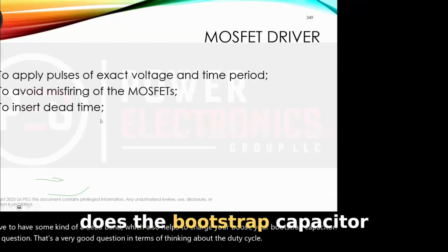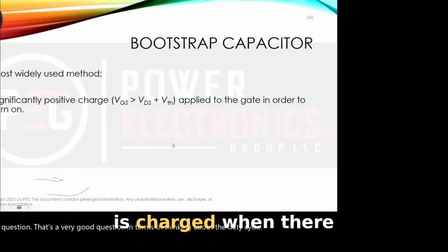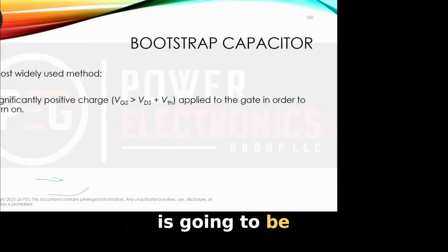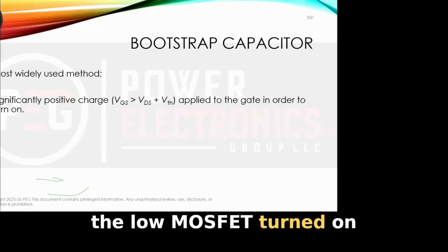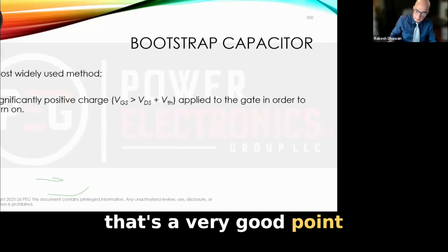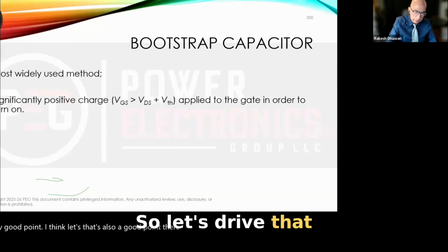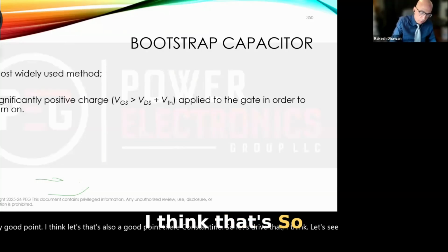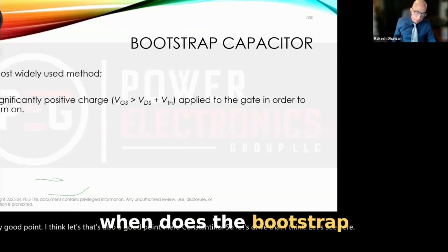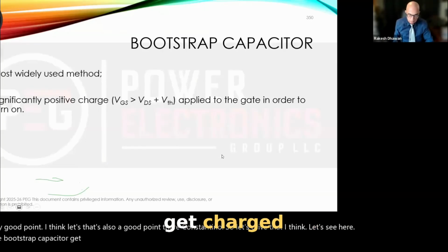Is the bootstrap capacitor charged when there is the dead time? I believe it is going to be charged when you have the low input, the low MOSFET on. Yeah, that's a very good point. I think that's also a good point there, Constantino. So let's drive that. When does the bootstrap capacitor get charged, right? So let's think about that for a second here.